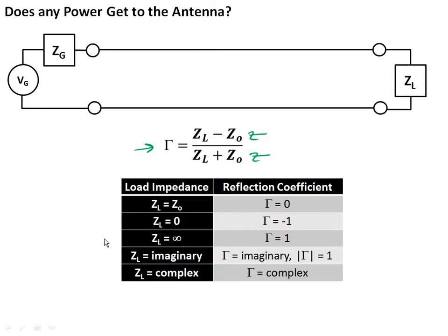We remember the reflection coefficient for a line that's open circuited, that essentially has nothing attached to the end. In other words, if we take this transmission line and remove a load, as we've done when we've stripped it off and turned those wires 90 degrees, the reflection coefficient is 1, and no power is going to be delivered. All the power is going to reflect back from the end of that transmission line and go back to the generator. So it's really a legitimate question to ask, when we take this transmission line, remove the load, and simply bend the wires, if we don't just have the same thing as an open circuited transmission line with a reflection coefficient of 1 and no power being delivered.